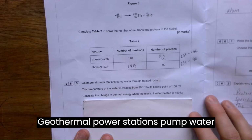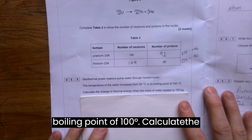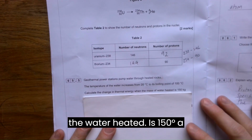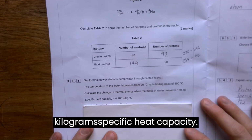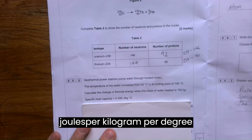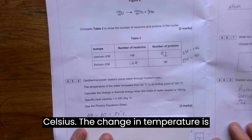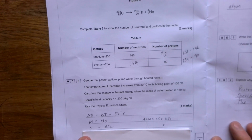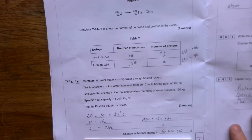Geothermal power stations pump water through heated rocks. The temperature of the water increases from 20 degrees to its boiling point of 100 degrees. Calculate the change in thermal energy when the mass of water heated is 150 kilograms. Specific heat capacity is 4,200 joules per kilogram per degree Celsius. The change in temperature is 80 degrees, 20 to 100. The mass is 150. Specific heat capacity of water is 4,200. 4,200 times 150 times 80 equals 50,400,000 joules.